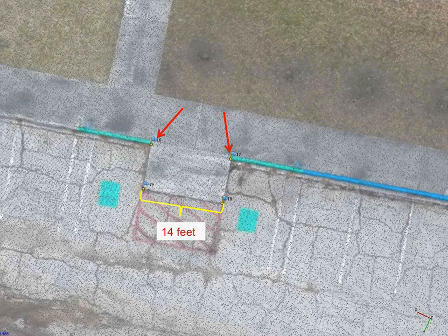So here's an example. This is zoomed in, and you can almost see the spaces between the pixels in this shot. We took GPS points on the 4 corners of a little ramp that goes into the parking lot, and also measured it with a tape measure. It's 14 feet on the ground. It's also 14 feet exactly within the point cloud. We also measured heights of walls and different things, and all of our ground measurements were exact within a few centimeters of what our point cloud represented. So we can create really accurate data, which is exciting, with a very low-cost solution.